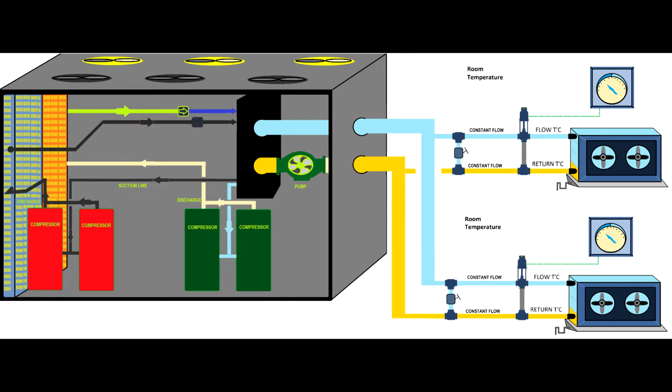What does it mean? By losing half of the capacity, the heat exchanger plate will lose its capacity too, and the water, the cooling agent, will get warmer. And if you have this type of valve which opens 100% and closes 100%, it will probably remain open, because the thermostat is set to a temperature and the air will never reach the set point, so the system will be continuously on demand.